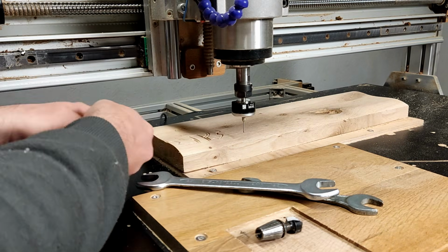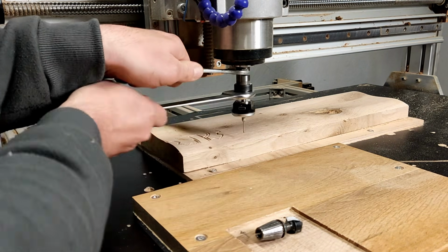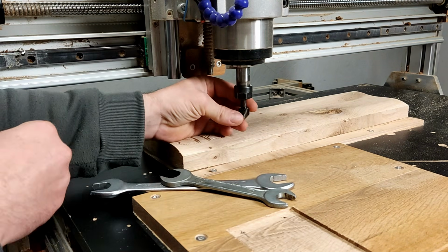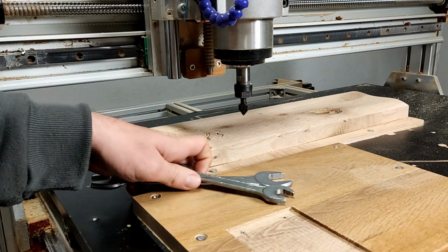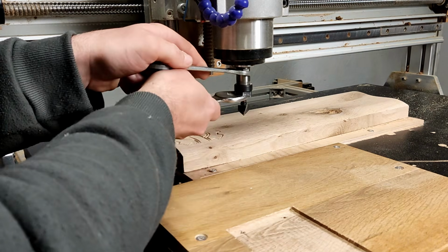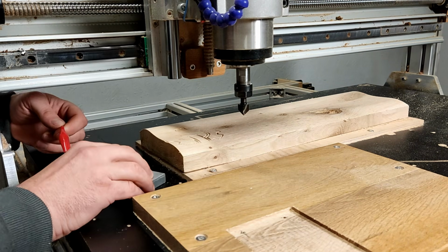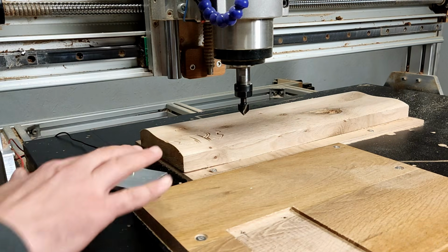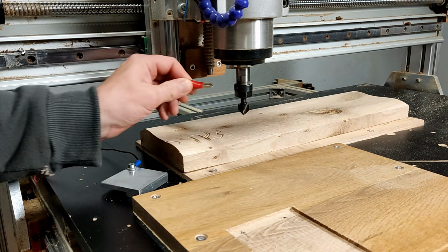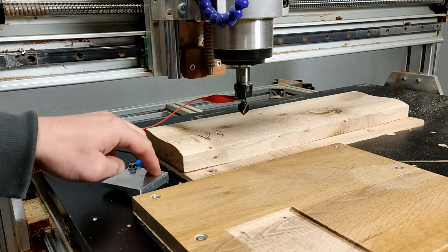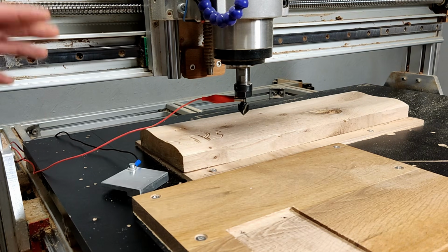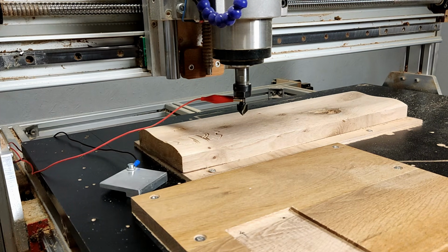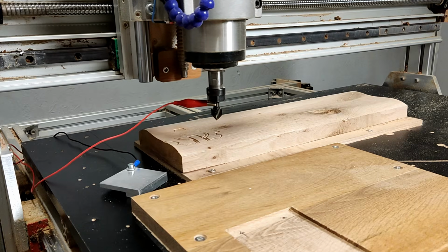Let's first unplug the probe, remove the probe from the spindle, fit the V-bit into the spindle, and then we will have to reset the Z value using the tool setter this time. Let's place the tool setter plate this time on the real value on the face of the table. You need to set the toolbit height exactly in the same place where you've set the probe's height. Otherwise, you might end up with some differences, which of course can create a lot of problems. So let's move the toolbit above the touch plate.